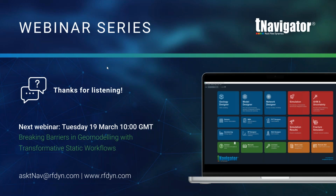Any volunteers to answer? Yeah, I mean, in the fracture simulator, you have the option of calculating the dynamic growth, if that's the question. Basically, and it is worth saying that when the fracture growth reaches the grid boundary, there are two options that the user can specify to limit the fracture propagation by the dynamic grid. One is by the dynamic grid, and the other option is to extrapolate the fracture beyond the grid boundaries. The fracture growth will be different depending on the option that the user has selected, but it's all incorporated within the 3D dynamic grid.